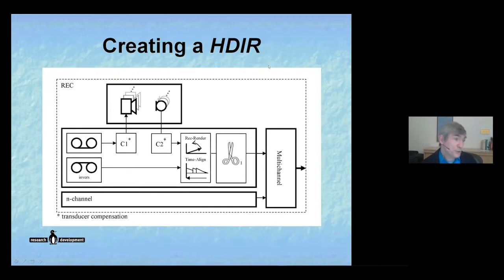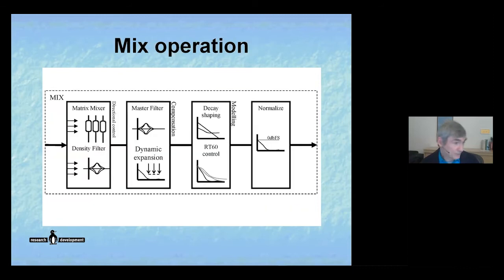So in order to create an impulse response, I also spend a lot of time in post-processing it. I developed methods to post-process. I can compensate to a certain degree for the deficiencies of the measurement speakers by compensating that in the C1 filter, and the deficiencies of the microphone in the C2 filter. By comparing them, I can cut it. To make it short, I work up to one or two weeks in the post-production of the IR before I give it to the artist.